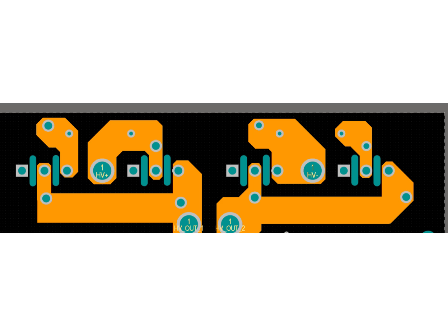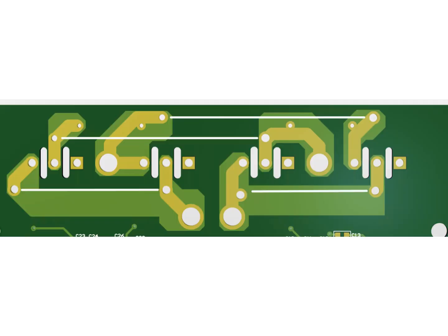In addition to the PCB copper width, a copper strip reinforcement facility is provided. Dedicated pads are placed along the midpoint route so that a copper strip or heavy copper wire can be soldered directly on top of the track, increasing the effective conductor cross-section. This provides additional margin for high current testing and continuous 3.3 kW operation, while keeping the PCB design flexible for prototyping and future upgrades.